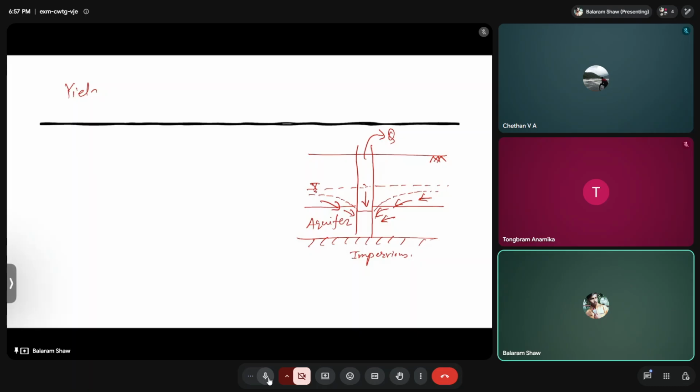That is just because the pumping rate is very high. So you should keep the pumping optimum, and also you should keep some lag time between pumping hours. Let's say if you do pumping for 30 minutes, you should wait for some time, which depends on the geologic condition and so on.